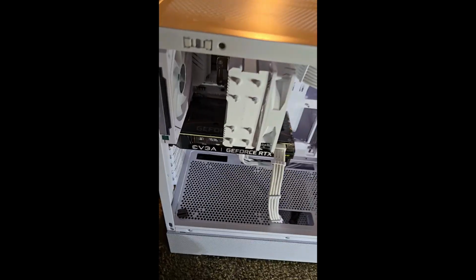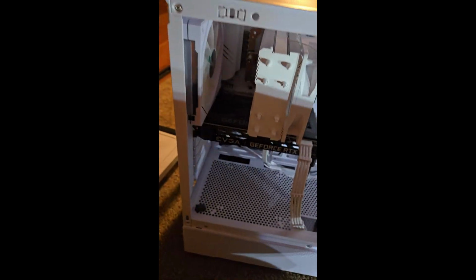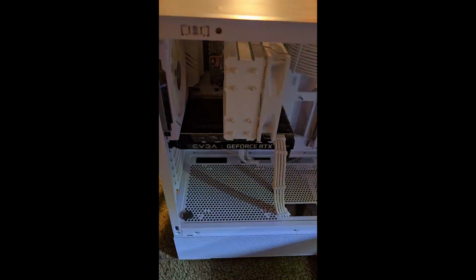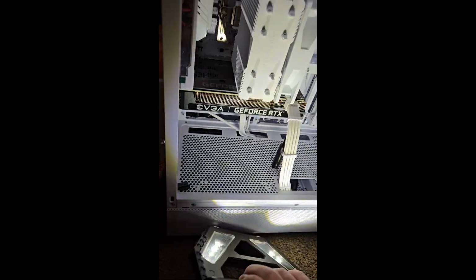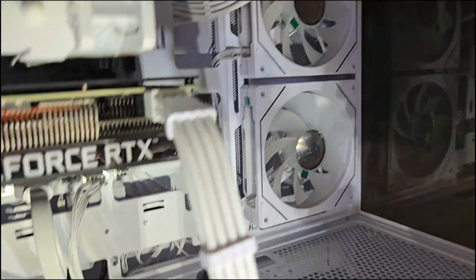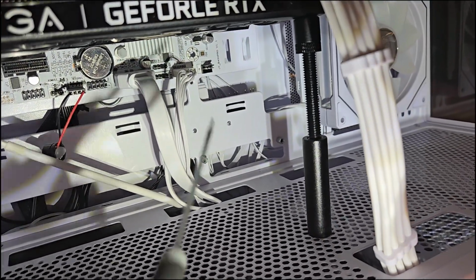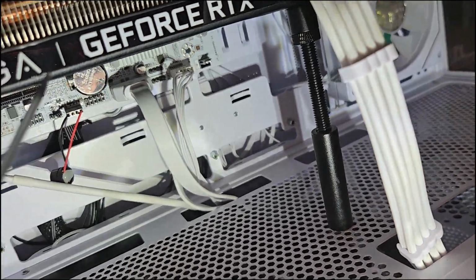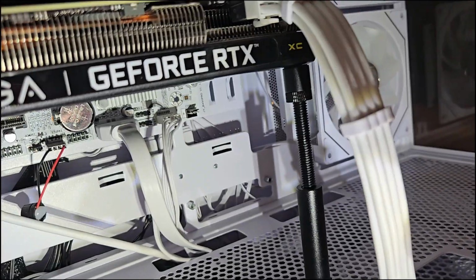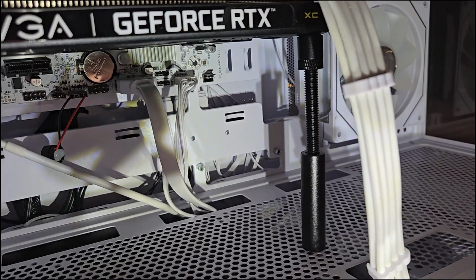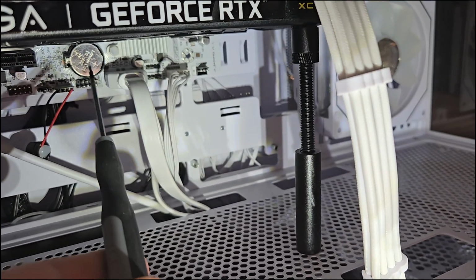Okay, going to want to get your side panel off. Now, some motherboards, I'm going to have to grab the light, give me a sec. Some motherboards have a reset button in the bottom, so kind of somewhere along over here or so, or even in the top. So if your motherboard has that, use that. If your motherboard does not, you're going to have to grab the rubber tip screwdriver, and we're going to have to undo this.